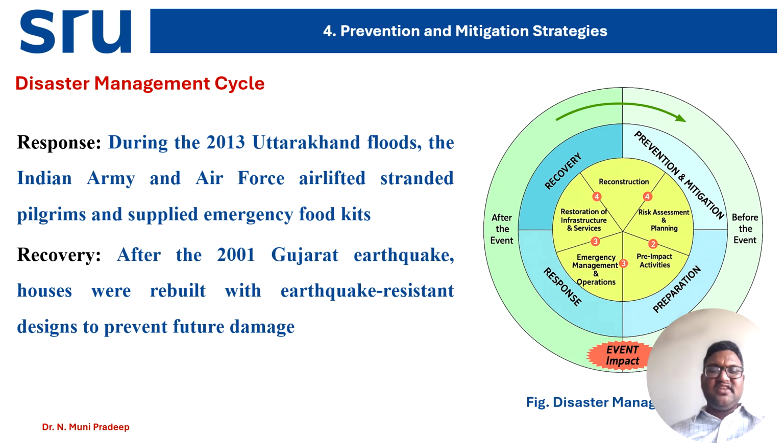Here, the Gujarat government gave financial support as well as technical support to the Gujarat people. So critically, the reconstruction incorporated mandatory earthquake resistant design features, which include appropriate foundations, reinforced concrete frames, proper structural connections and masonry wall construction practices that could withstand future seismic events.